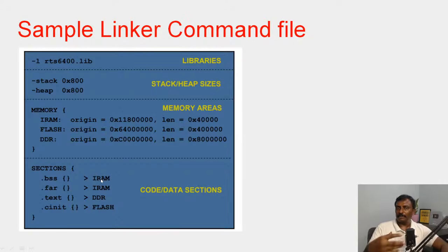When you write complex code, like audio processing or video processing applications, it definitely won't work without writing the linker script. You will get a memory map error while linking, when you generate the final ELF file, the executable linker format file, or sometimes a hex file. The ELF file will not be generated without giving the correct configuration to the linker.